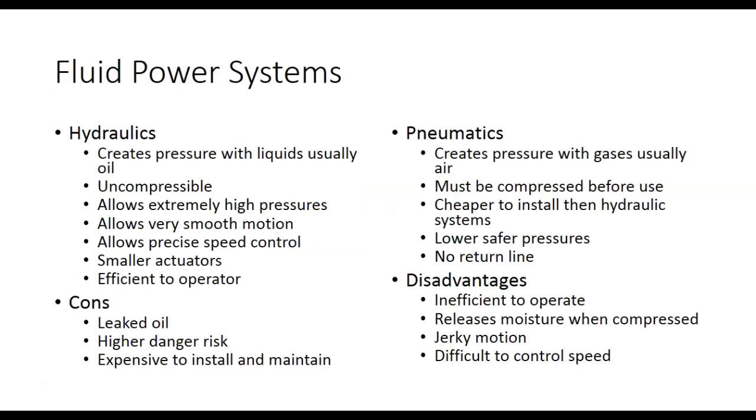So fluid power systems, hydraulics, creates pressures with liquids, usually oils, but you could use water. In fact, some people do use water, but they'll put lubricants in it because water is very, very corrosive on metals, right? So it's incompressible. We consider it to be incompressible. So that means if we had a cylinder and we put something in there and we tried to push down on it, you couldn't, because you cannot compress it.